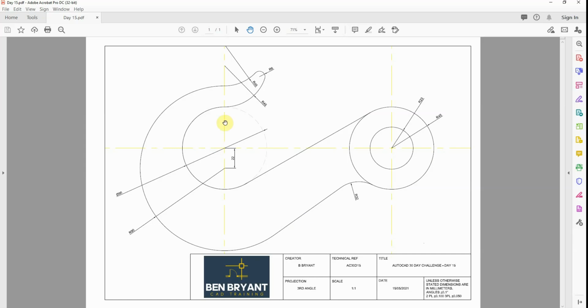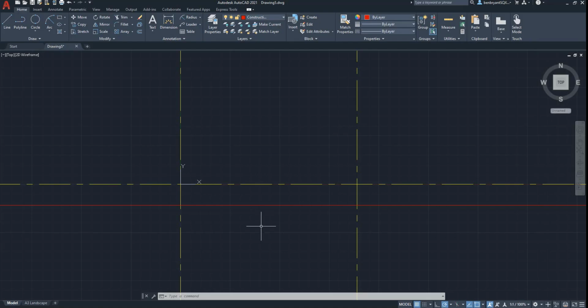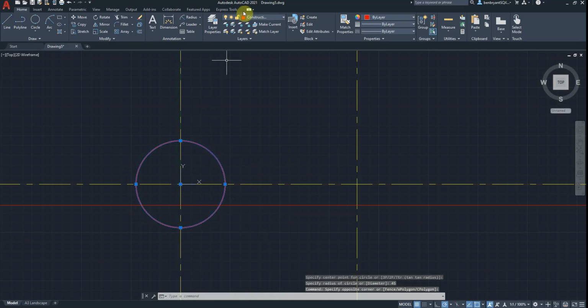So that's fairly straightforward. I've got an R90 from the centre point, so diameter 90, R45, and then I've got an offset of R90 from the 22, and I've got an R23 and R45 from the second centre point. So come in, use the circle tool, select my diameter, so this is going to be 45. Also you need to change that into my drawing, and then change my layer back to drawing like so.